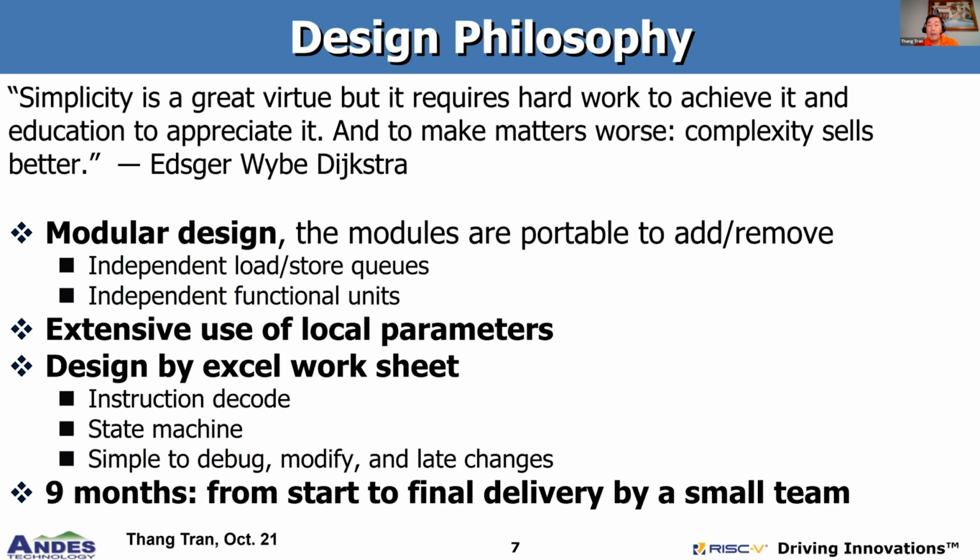We also use Excel in our design with a script to convert the Excel to Verilog case statements. This actually is not new. We used to design with a truth table in Espresso or PLA. The advantages are listed here. One of the examples is the issue state machine for issuing micro-ops over multiple cycles.